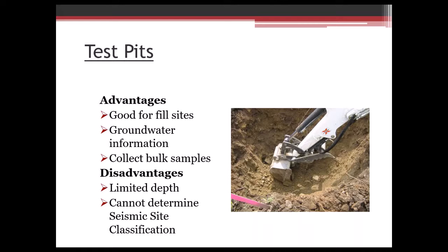Certainly a test pit, sometimes advanced on a site where groundwater is going to be tough, maybe during a pre-bid meeting, gives the contractor an idea of how fast water is going to flow into the hole, so they can determine how they're going to advance their project and their foundation excavations. The other thing that we do a lot with it is collecting bulk samples that we bring back for lab testing. Disadvantages: you're limited in depth.